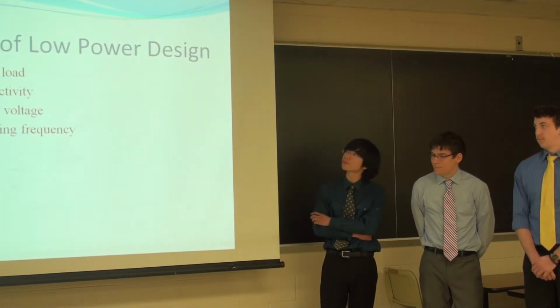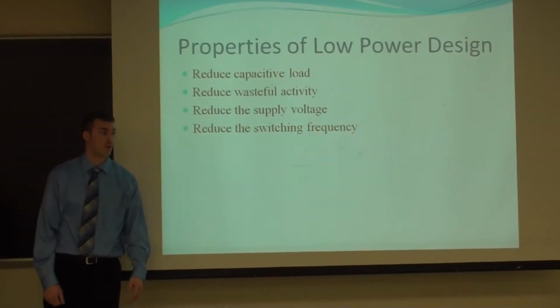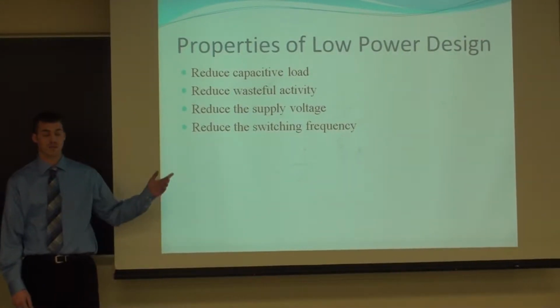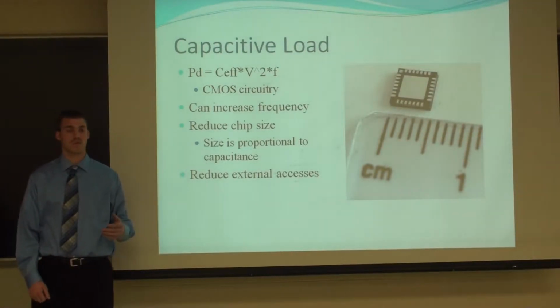All right, Tim and I are going to talk about the properties of low power design, which include reducing capacitive load, reducing wasteful activity, supply voltage, and switching frequency. I'm going to start off with reducing capacitive load.